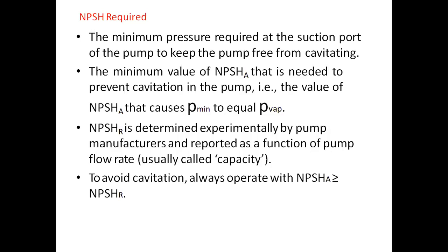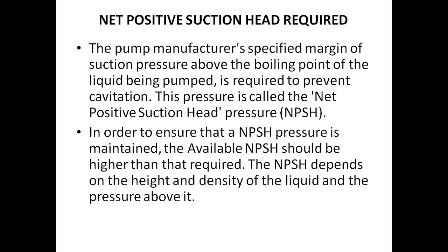The minimum value of NPSH, however, that is needed to prevent cavitation in the pump, that is the value of NPSH that causes P minimum to equal P vapor. So NPSH required is determined experimentally by the pump manufacturer and reported as a function of pump flow rate.